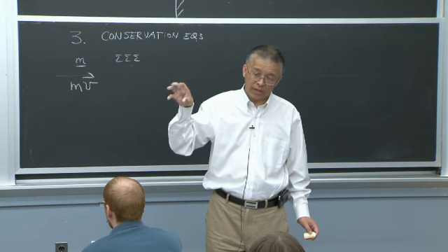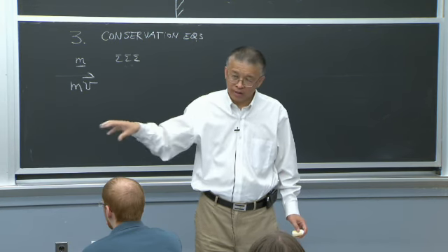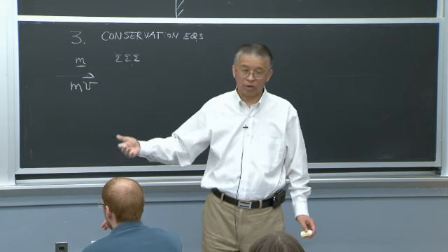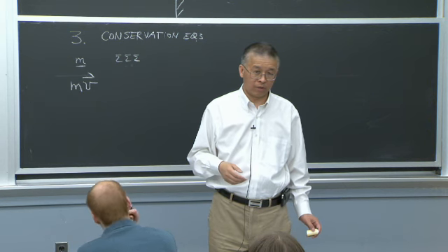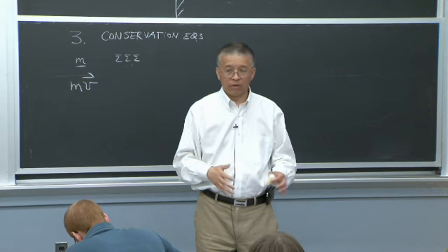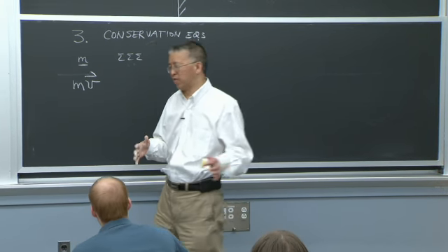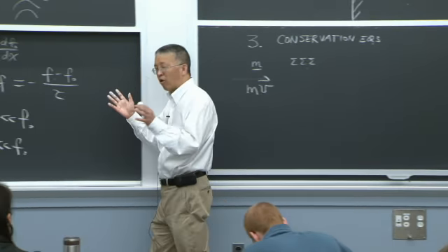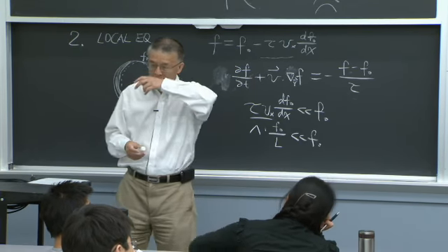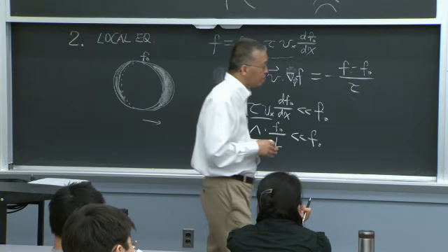So you see here, you are still using an approximation. The Navier-Stokes equation is an approximation because you approximate the Newton shear stress term there. And the same you can do for energy. On this side, fluids have higher-order moments, and you can do higher-order moments and modifications to the Navier-Stokes equations.